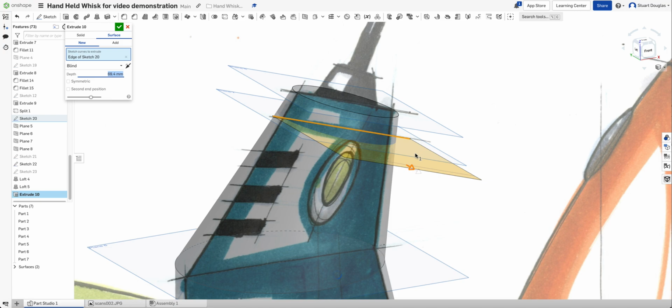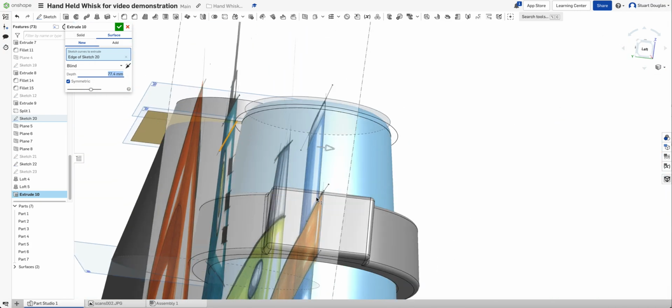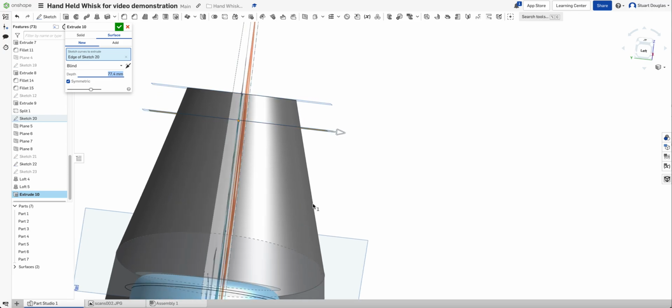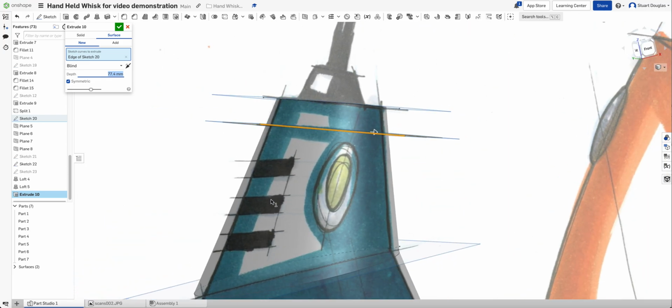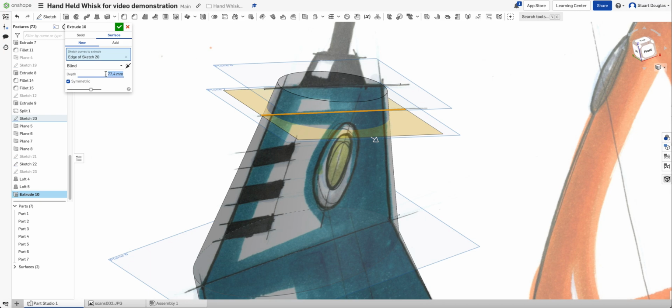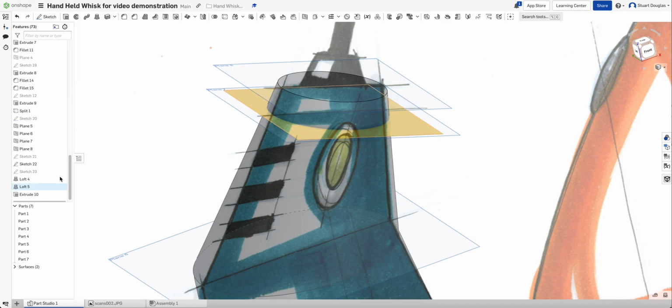Now a surface has no thickness, and it doesn't 3D print or anything like that. We use it to extrude to and to manipulate our work. Now what we want to do is create a symmetrical surface, and the surface must be bigger than the outer of our profile. So let's spin it around. You can see that that is now bigger than the top. So that is fine. I don't have to worry about the distance, and we're creating a new surface. So let's accept that extrude temp.